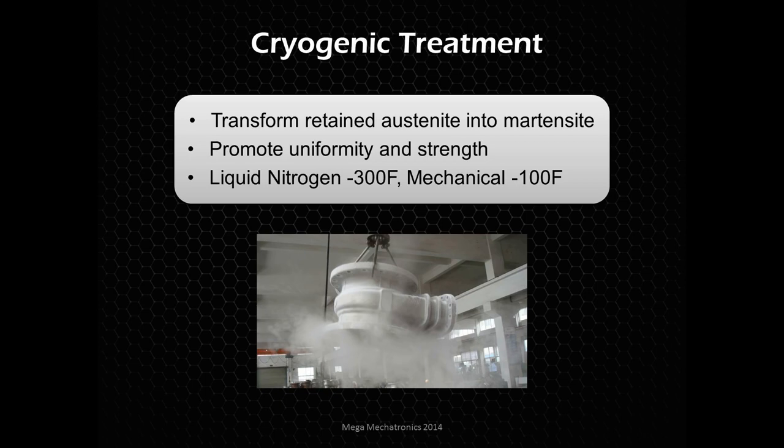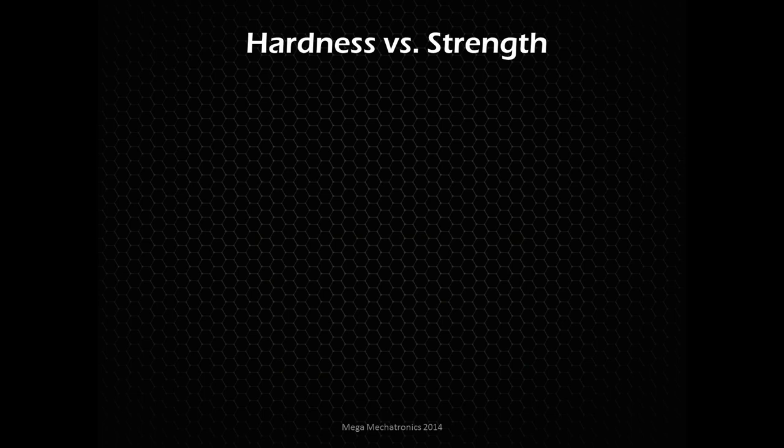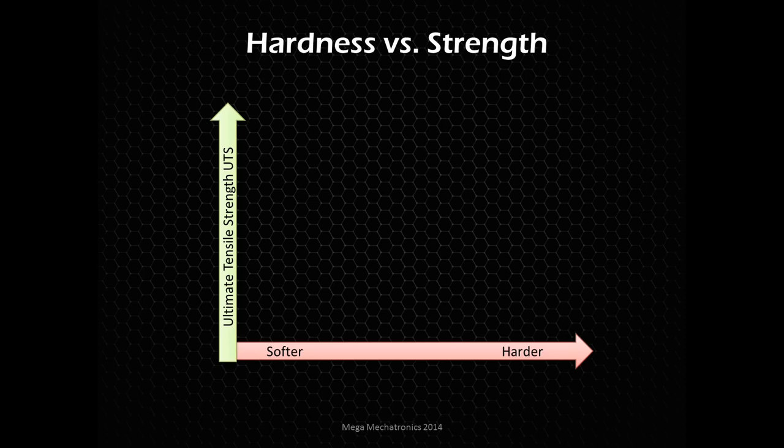Hardness does correlate with the strength of the material. There is definite correlation. We're looking at strength here, ultimate tensile, and then the hardness at the bottom. As the hardness goes up, so does the strength. And you'll see this with tests, specific tests of different alloys, if you were to research that.